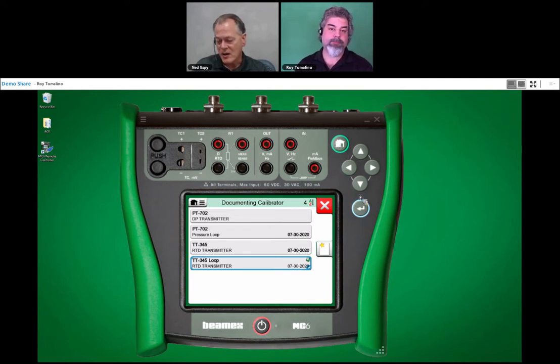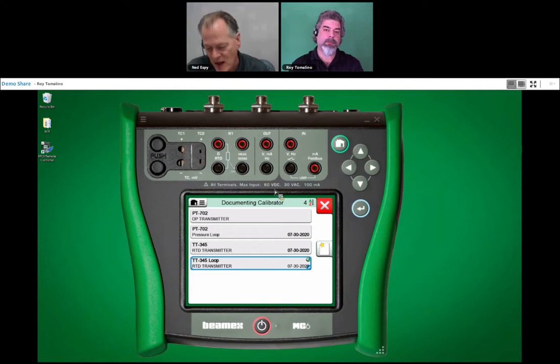Some comments here. You were doing a partial loop test. You were simulating into the transmitter. So ideally, you would have liked to have been able to pull the RTD out of the process and maybe drop it into a dry block. Yes. Or bath and simulate those temperatures and then call the control room and see what they were reading. Nowadays, a lot of people even have the ability to see the DCS readout on their phone.